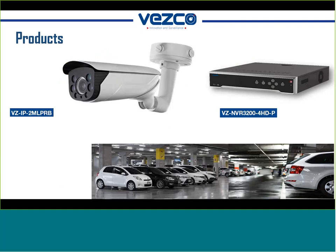All right, so let's go ahead and take a look at what our products are. Today we offer 2 products, which are a camera and an NVR that's compatible with that function. Our camera is called the VZ-IP2ML-PRB, and our NVR is the VZ-NVR3200-4HD. We have the version that is just 4HD, and we have the version that is 4HD-P. The difference of the two is that one does not have PoE ports, and the other one has 16 built-in PoE ports. This NVR supports up to 32 cameras. So that means that I can have up to 32 LPR cameras.